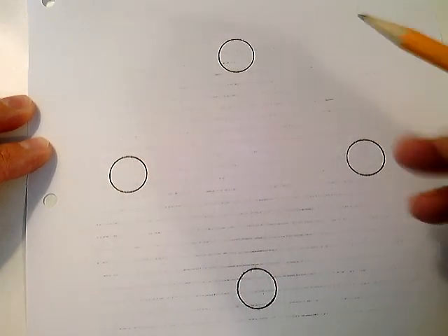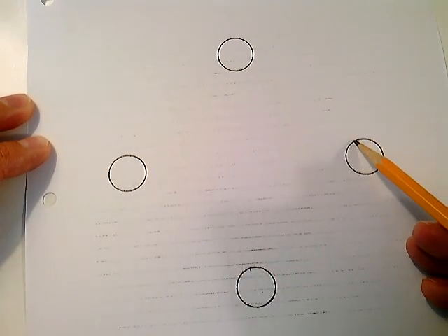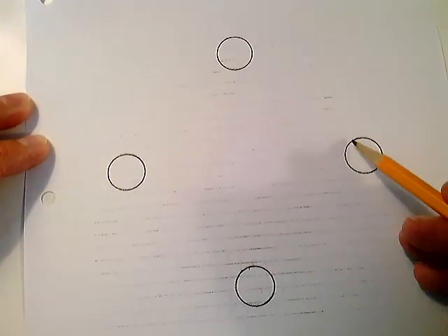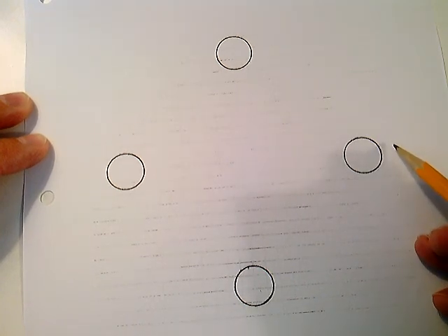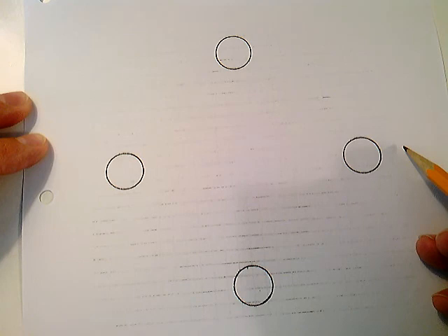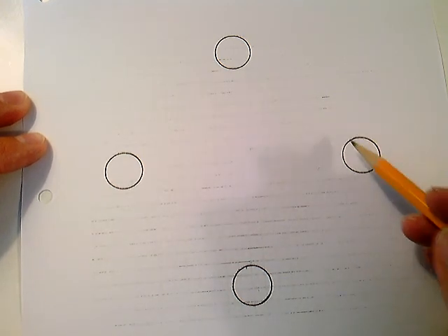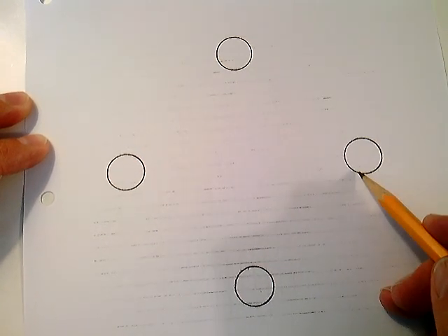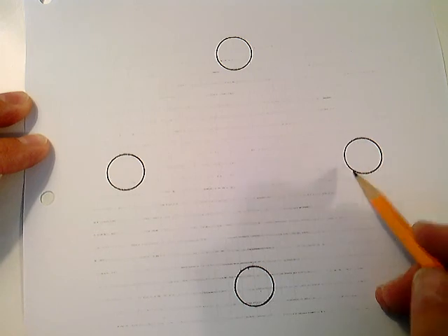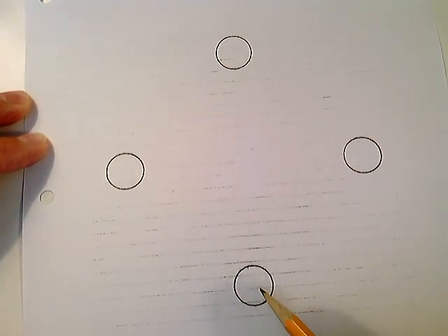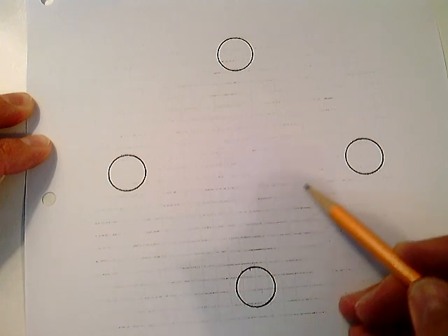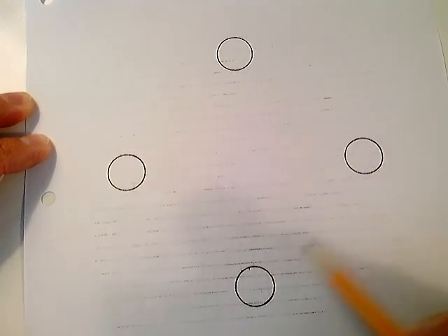So you're going to draw an arrow from here to here. When ready goes to a 1, when that tire is on that pressure sensor, you're going to go down to here, and you're going to go into your pre-soak state and your rinse state, but it's going to be the pre-soak. And then when you get to a particular count as an input, well, what count? Well, count goes to 2. You're going to move down here, and this is going to be your wash state. Then when you go to count 4, and the counter's going to tell you when you're count 4, look what happens. You come back to this state because it's going to do your rinse.